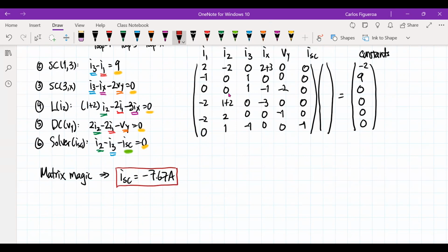So now that I have I short circuit, that tells me that RTH should be VOC divided by I short circuit. So this should be minus 79.3 volts divided by 7.67 amps. That gives me a positive 10.3 ohms for RTH.